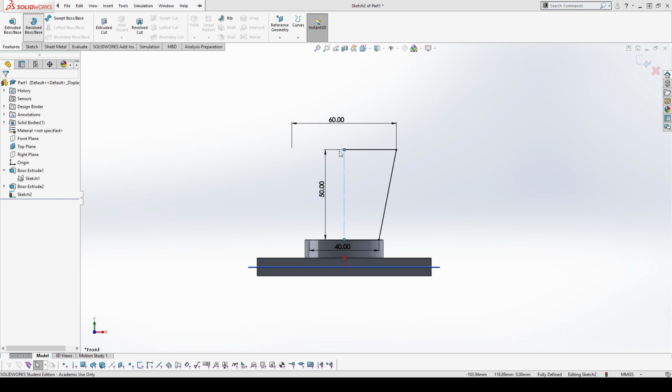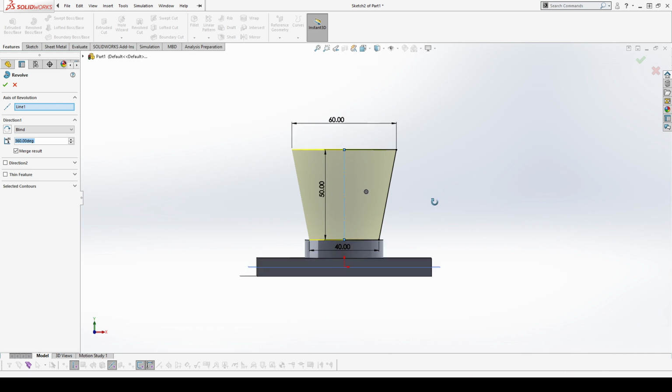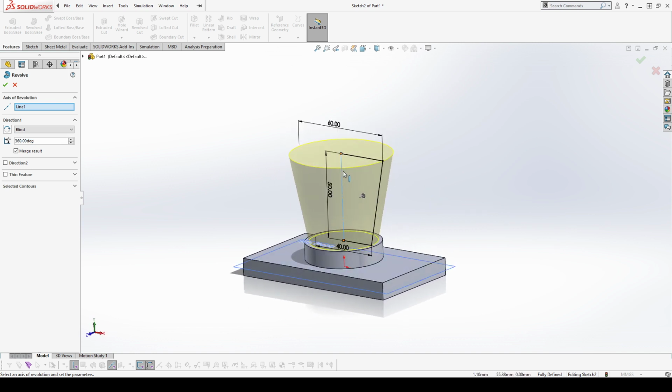It's going to give me this message here, which you won't see in the stream, unfortunately, but it says sketch is currently open. A non-thin revolution feature requires a closed sketch. Would you like the sketch to be automatically closed? So it's basically telling me that I don't have a closed section of geometry, so a watertight path of non-construction lines in my sketch, and it wants to close it for me. And what it's basically going to do is draw another line in the sketch on top of this construction line that is a solid line. So I can just click yes, and you can see that because I only had that one construction line, it's like, all right, that's probably the line that we want to revolve around.